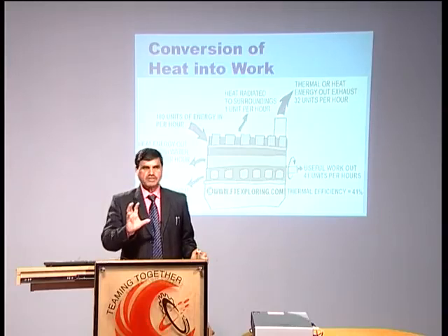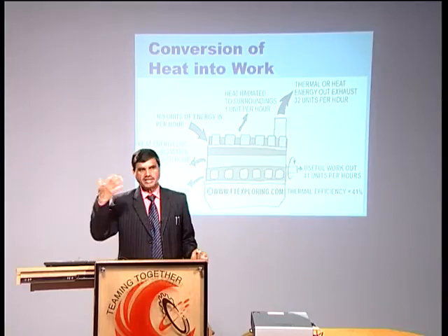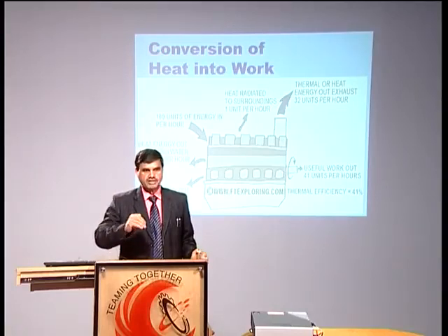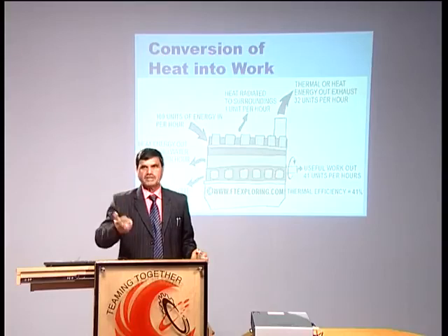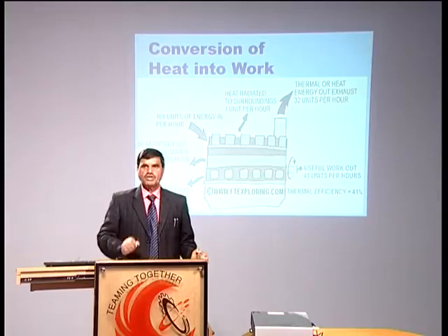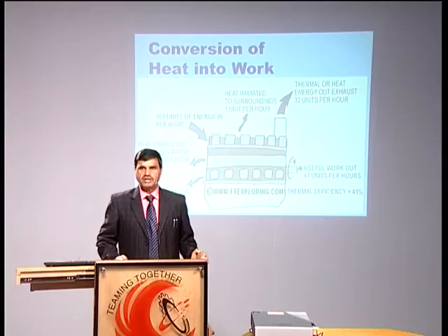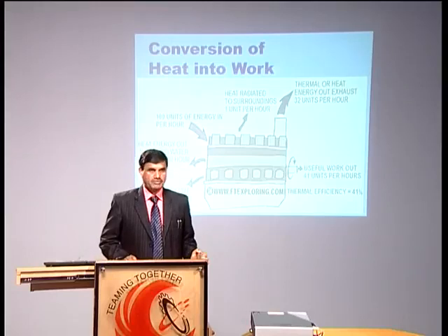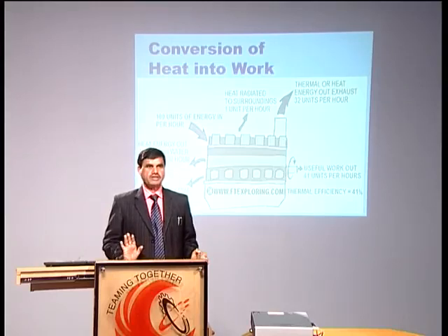Then, because the temperature of the cylinder is significantly higher as compared to atmospheric conditions, some of the heat is rejected due to radiation and some by direct convection also. So heat radiated to the surroundings is 1 unit per hour, which is again wastage of heat. And the burnt products, after combustion during the exhaust stroke, have a temperature higher than atmospheric.